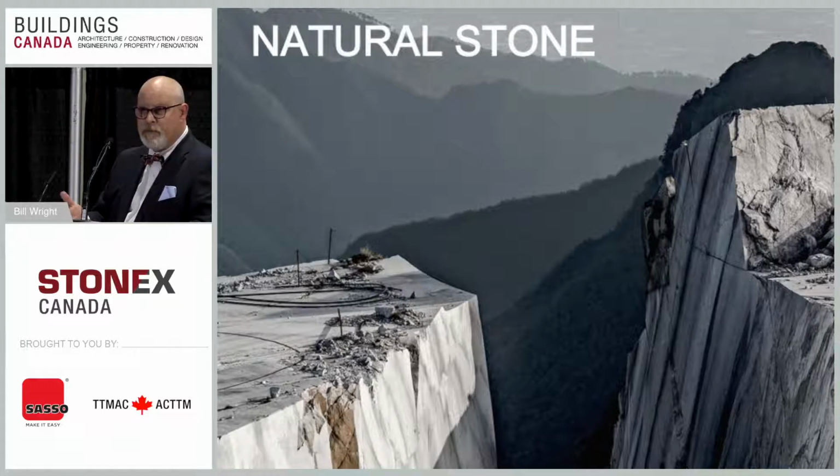Again, we talked earlier about the shade variation, the natural markings. We want to make sure that there are no fissures, there are no cracks. We don't want any big marks or spots. If these things are naturally inherent in the stone, they need to be looked at, like I said, in a large range, and at least put in the specification or have control samples available so that people know what to get.